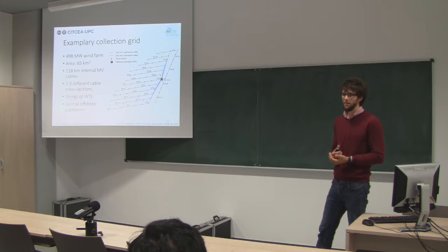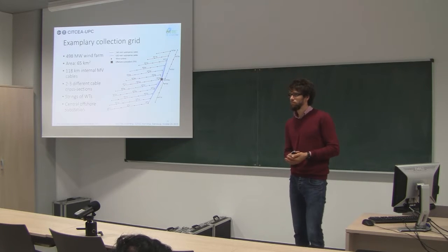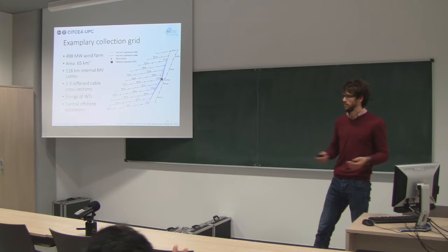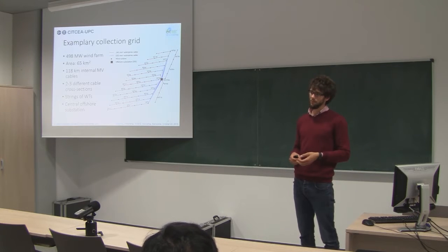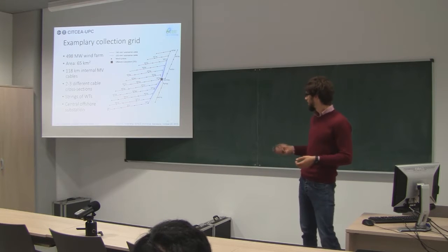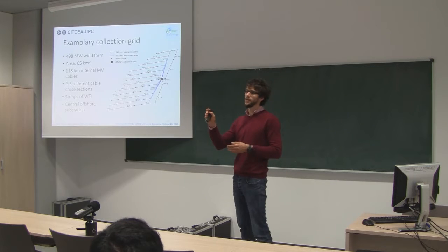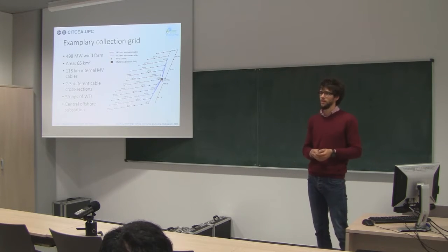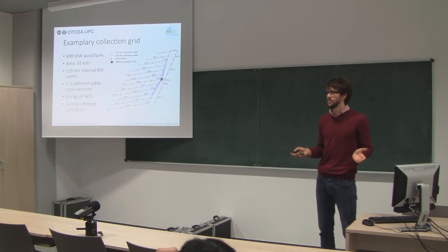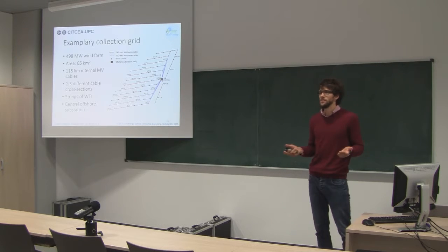Maybe there are conventional cross sections. That's one reason, yes. It's standardized. And there is a typical length of cable, though you can ask the manufacturer to build them in any length you want. But when they lay the cables, maybe it's easier not to interrupt, so they can lay continuously the same type. That's also a reason, because anyway you connect your cable to one turbine, then go down to the ground, and go up in the next turbine, connect it to the bus bar, and then you have a new cable connecting. So you can't do it continuously, but there is some installation benefit. Think about having to install only 2 cable cross sections. Maybe it's easier if you have only 2 types. But the main reason is economics.